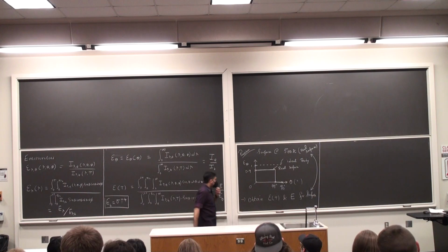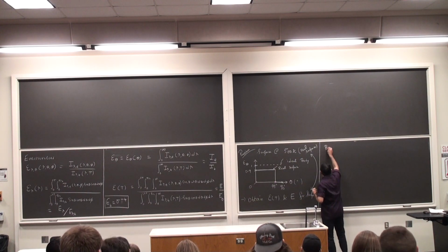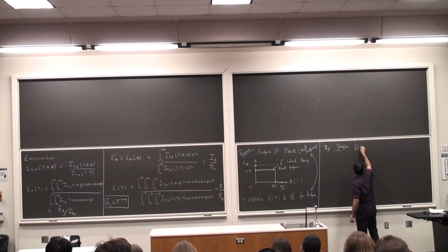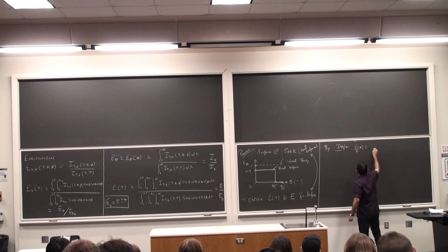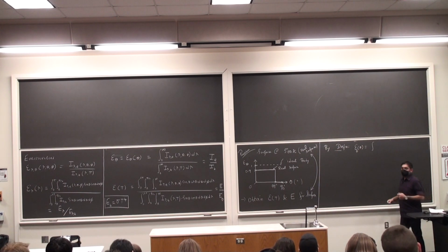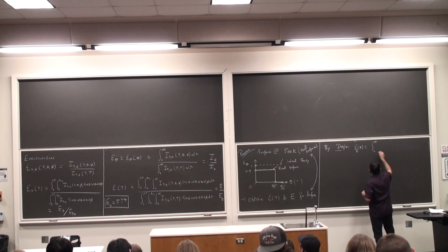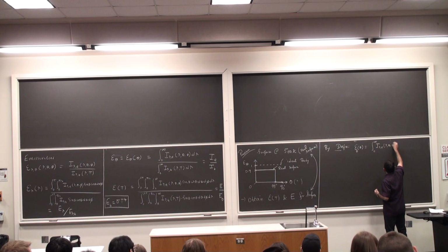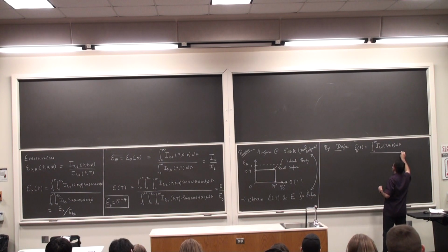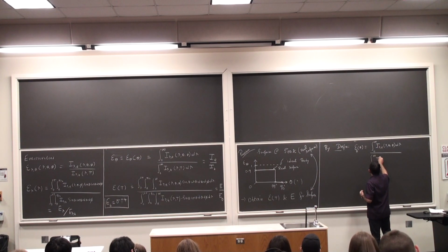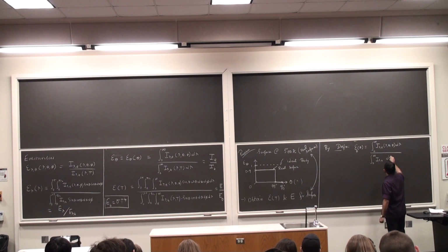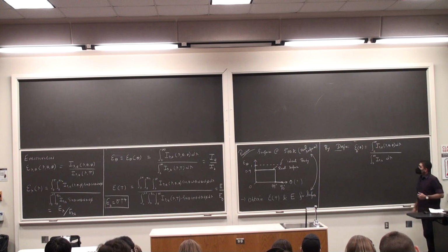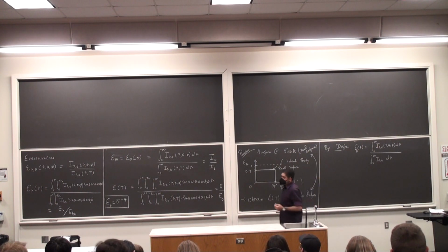By definition, epsilon theta is the integral from 0 to infinity of I lambda comma e d lambda, divided by the integral of I lambda comma b d lambda. We are asked to find epsilon as a function of temperature.